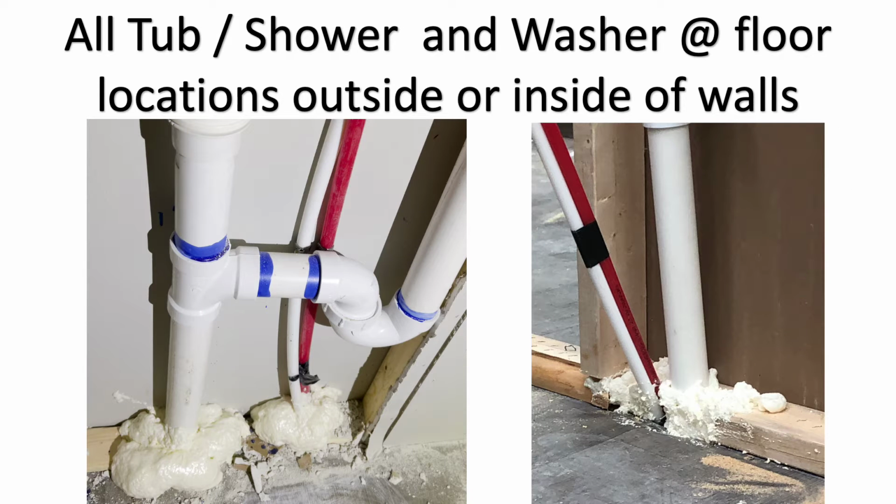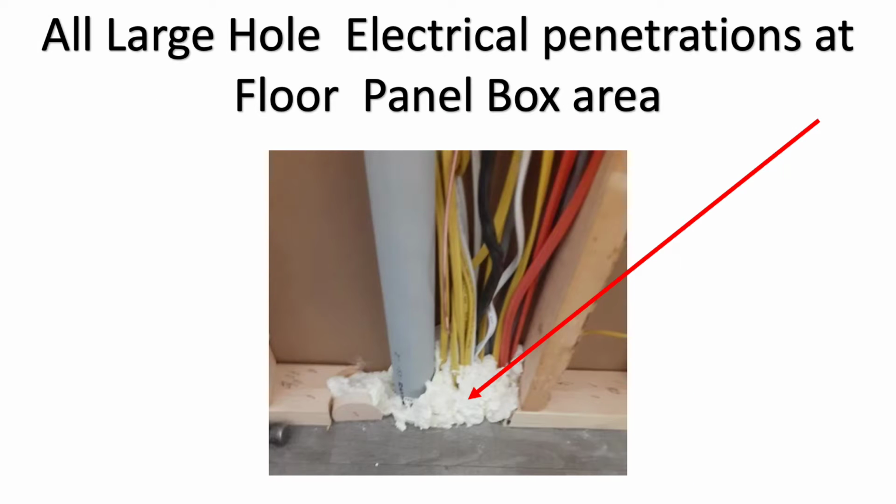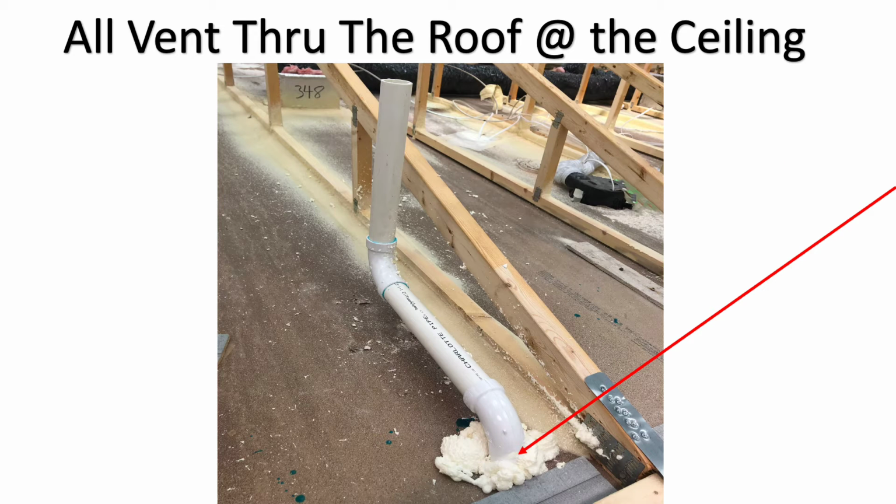All tub and shower and washer floor locations, outside or inside of walls, must also be foamed for air infiltration. All large hole electrical penetrations at the floor panel box area should be foamed for air infiltration. All vents through the roof at the ceilings should be foamed as well to prevent air infiltration.